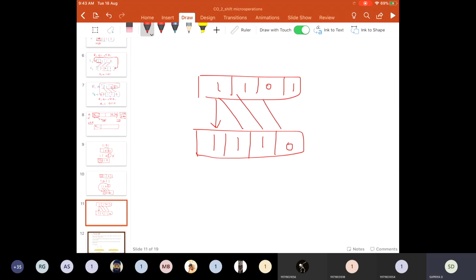Okay, arithmetic shift right. The most significant bit is directly shifted without any modification. The most significant bit is shifted directly, that is the R minus 1 bit of a given register is shifted as it is. There is no change in it. And for the next bits, to form the arithmetic shift right, you are going to shift 1 bit right from the R minus 1 digits.